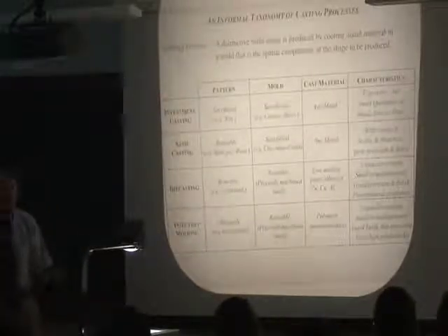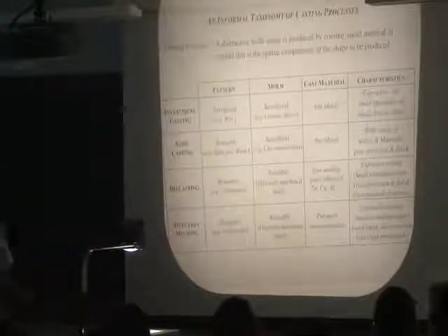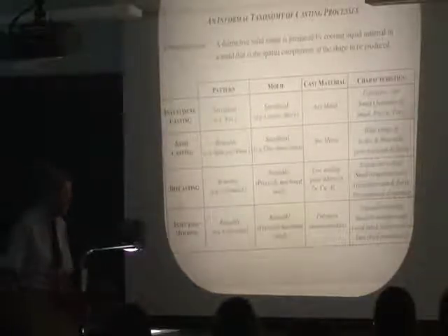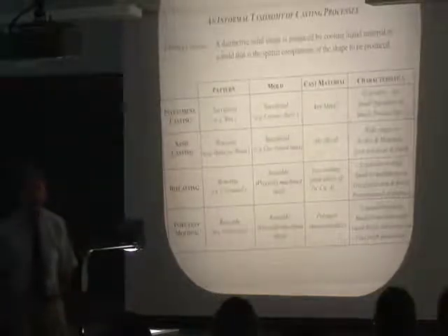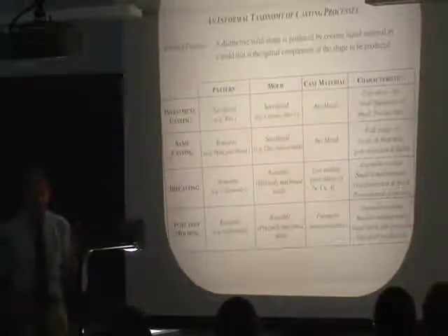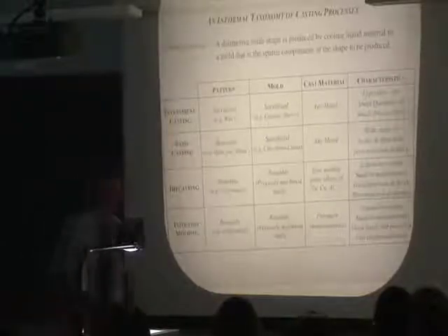If you were taking apart power tools in the lab, almost certainly quite a number of the components were injection molded. And you ought to be able to see this with little circles which were the pins that push the thing out of the mold.